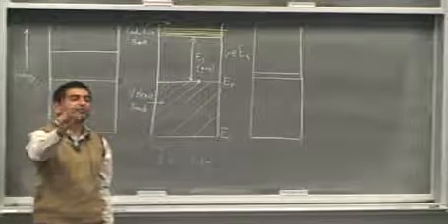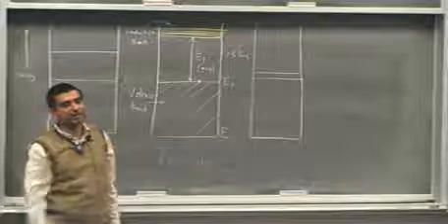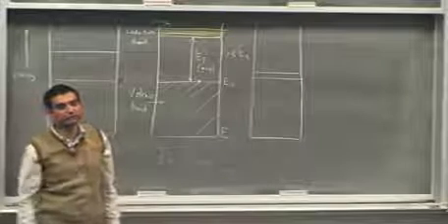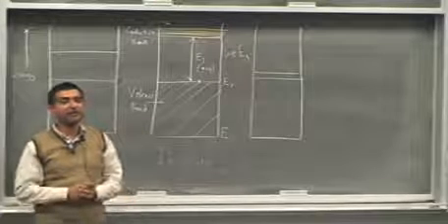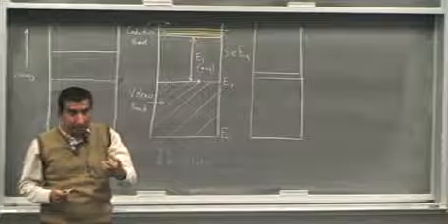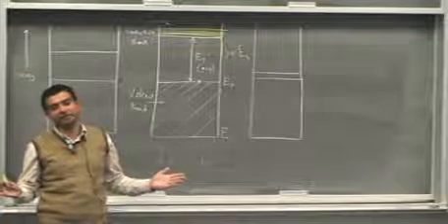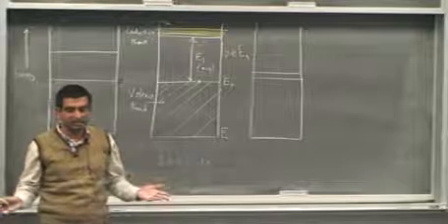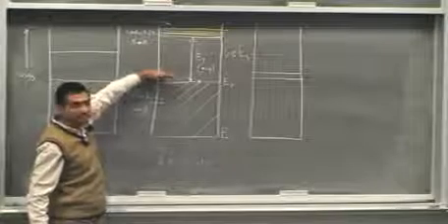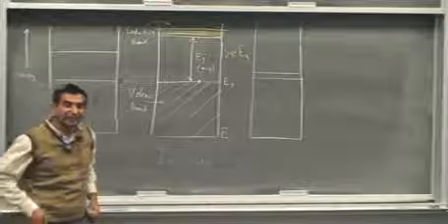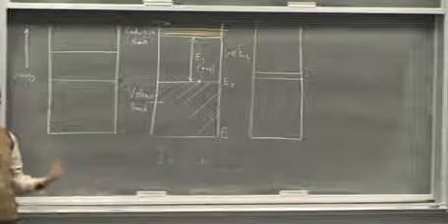A capacitor that you use in your electrical engineering laboratory is rated for a certain voltage. A 5 volt capacitor, a 20 volt capacitor. When you look at power systems, a 240 volt capacitor. Because if you give more than this much voltage, the dielectric material in the capacitor will break down and it will no longer remain a capacitor, it will become a conductor. So when you supply enough energy to overcome this band gap in an insulator, the insulator starts conducting.